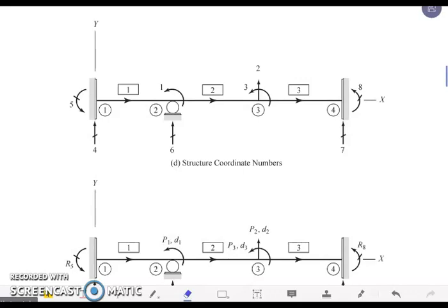In our previous discussion, we have a symbol, an arrow, to identify our degrees of freedom and an arrow with a slash for our restraint coordinates. So it is the same symbol that we're going to make use of. We have an arrow, of course, for rotation. For member 2, we don't have translation for a roller, but there is rotation. So we now have 1 degree of freedom. This will be the symbol, an arrow that is in curvature, an arc. That will be our 1 degree of freedom in rotation.